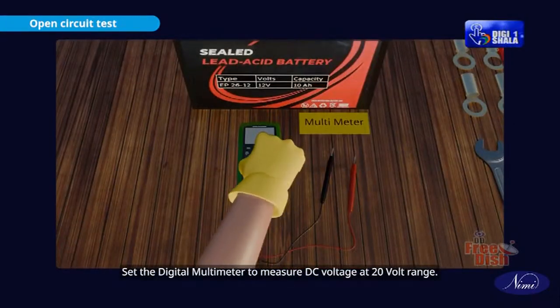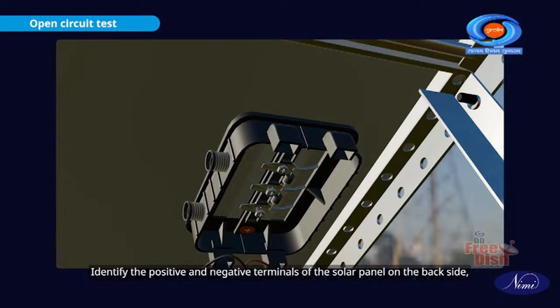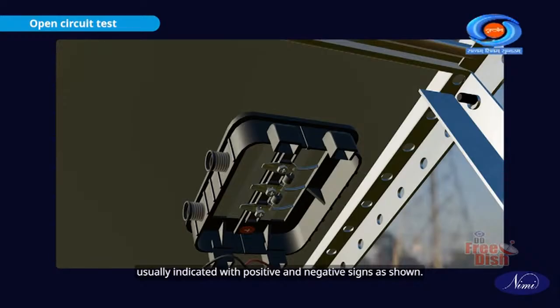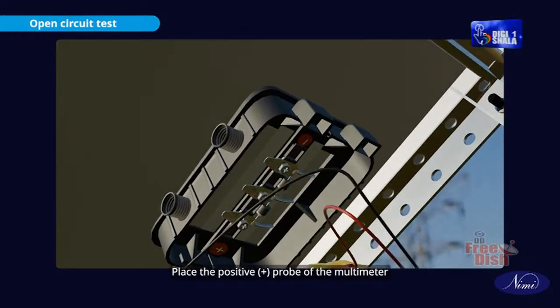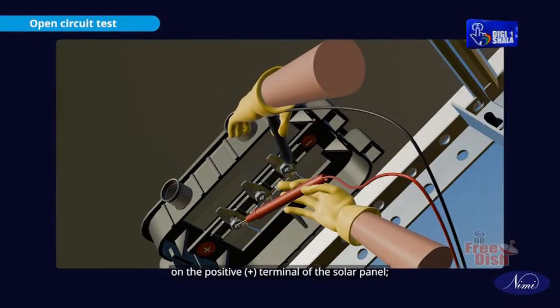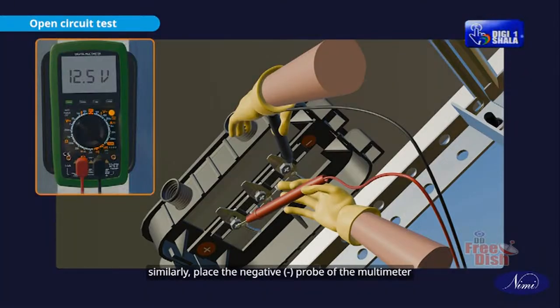Set the digital multimeter to measure DC voltage at the 20 volt range. Identify the positive and negative terminals of the solar panel on the back side, usually indicated with positive and negative signs as shown. Place the positive probe of the multimeter on the positive terminal of the solar panel. Similarly, place the negative probe of the multimeter on the negative terminal of the solar panel.